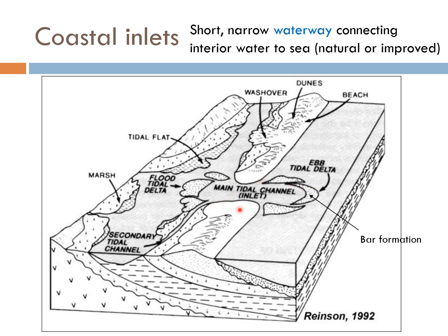may be constructed here. The jetties will be able to intercept the longshore transport so that the sediment does not block the inlet. Besides that, the jetties also allow any upstream discharge to flush out through the coastal inlet such that it is able to maintain sufficient depth along this narrow waterway.